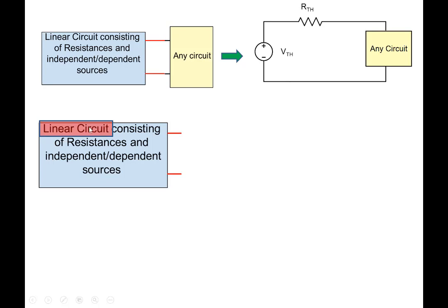And so let's explore this. Because it's a linear circuit, for the time being, let's say this is the voltage here and this is the current here. Let's say current going in and the voltage is over here. So please note that what we are saying is that this part of the circuit here is equivalent to this part from the terminal point of view. Okay, we're not saying that inside everything is the same, because this circuit doesn't capture what is inside it, right?